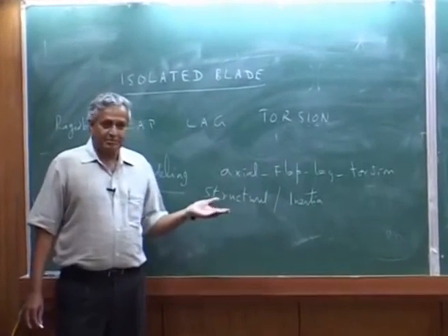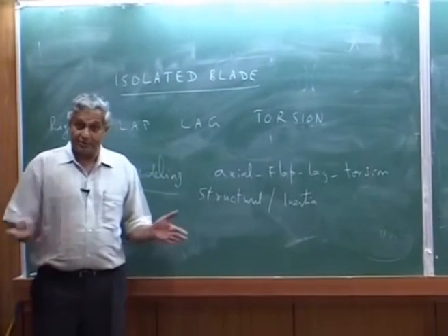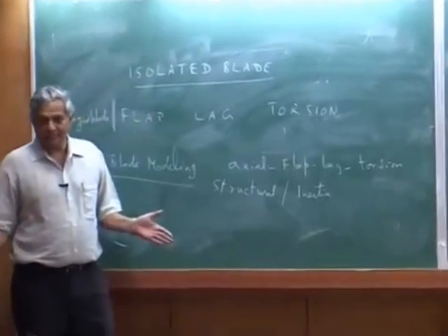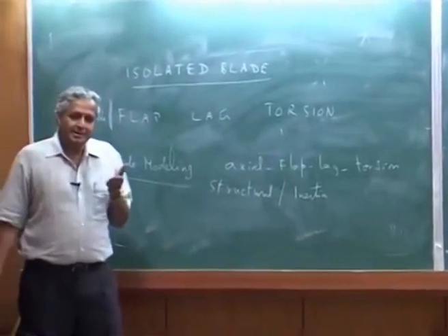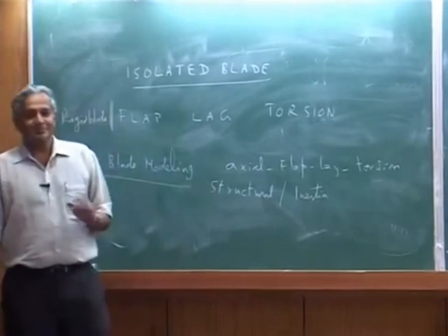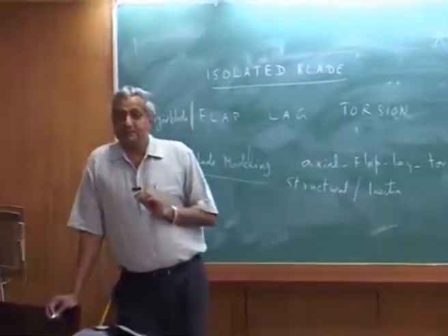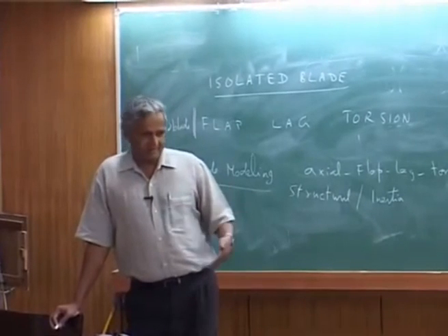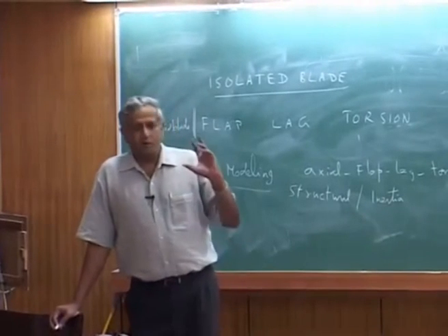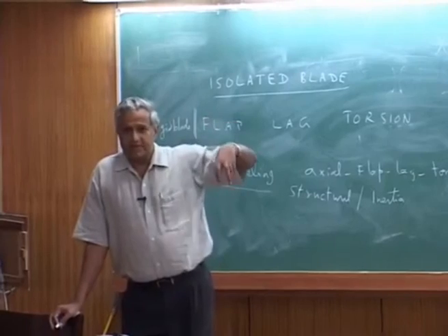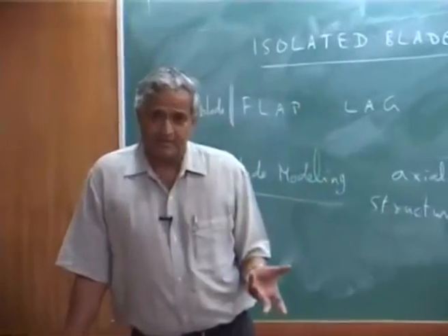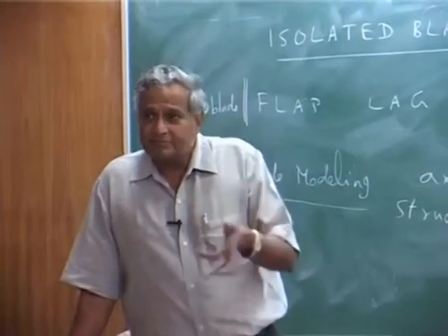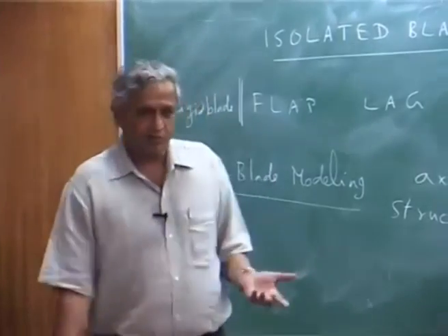Another one: aerodynamic modeling is required if you want to solve the aeroelastic problem. Traditionally, people use a relatively simplified aerodynamic model. Of course, simplified in the sense of quasi-steady with dynamic stall, with some dynamic wake, etc. Because that's what we have used.